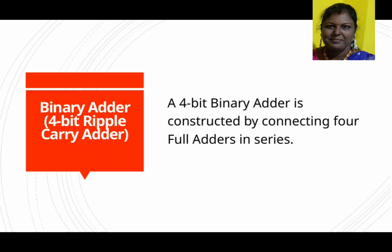Let's talk about building a 4-bit binary adder. We do this by linking 4 full adders one after the other, in a chain. Each full adder handles 1 bit of the numbers we're adding. This setup is called a ripple carry adder because the carry output from each adder ripples down to the next. It's a simple, effective way to add 4-bit binary numbers, bit by bit, in sequence.